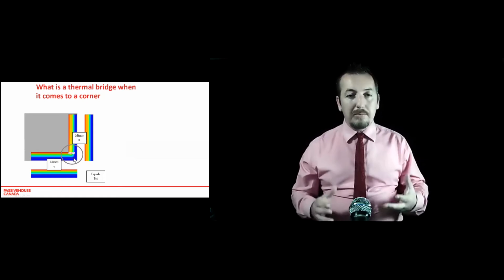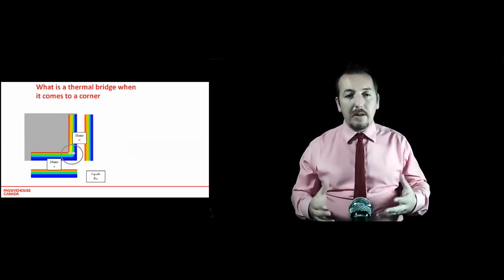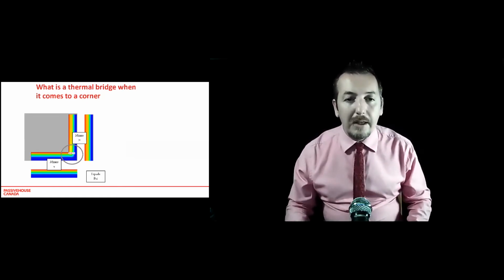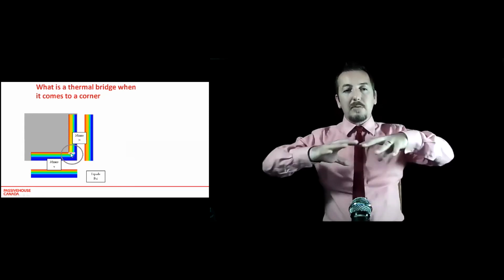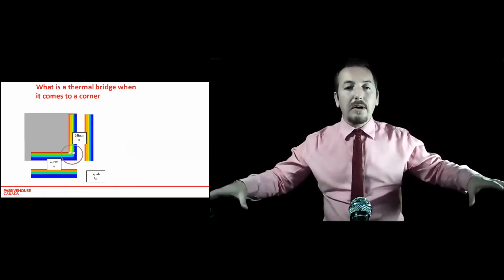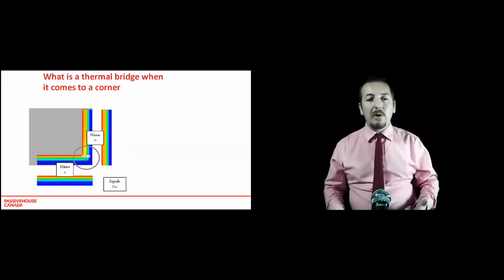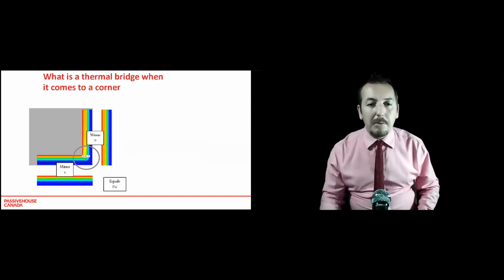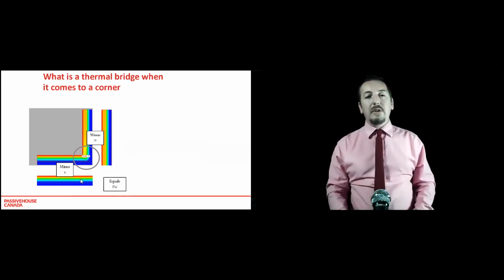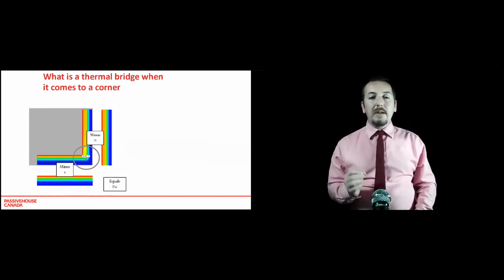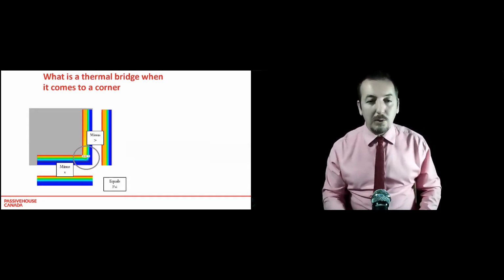And plainly, due to the fact that it's just a corner and that it has more surface area on the outside than on the inside, heat's able to spread out from that corner to a bigger surface area on the outside, thus giving more heat flow. But because PHPP overlaps the dimensions, it has some allowance for that. And if you get a minus psi value in PHPP, now you know what that's doing.